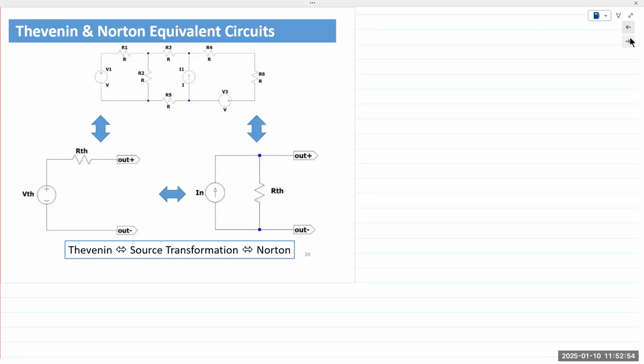This is a very important concept. As an electrical engineer, you would use this again and again and again throughout your career. Okay. Now, having said that, we are not going to analyze very complicated circuits, but you would use Thevenin and Norton to quickly analyze some portion of a circuit and find the Thevenin resistance and the Thevenin voltage being applied. Simple reason is this.